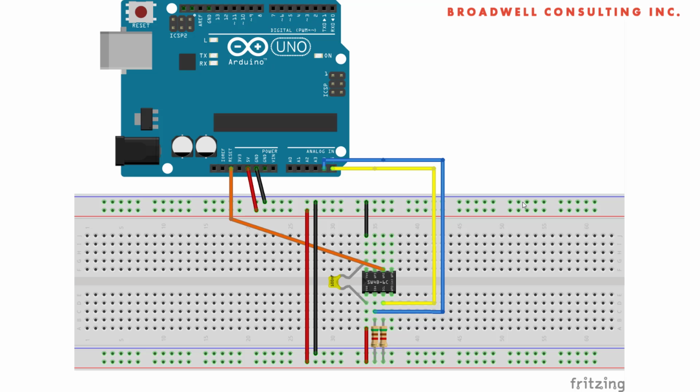Today, we're going to be looking at how the Serial Wombat Watchdog function can increase the reliability of systems. In this case, we have an Arduino Uno that's attached to the Serial Wombat. It's driving it via I2C, and the Serial Wombat's pin number 2 is attached to the reset pin on the Arduino Uno. This allows the Wombat to reset the Arduino.